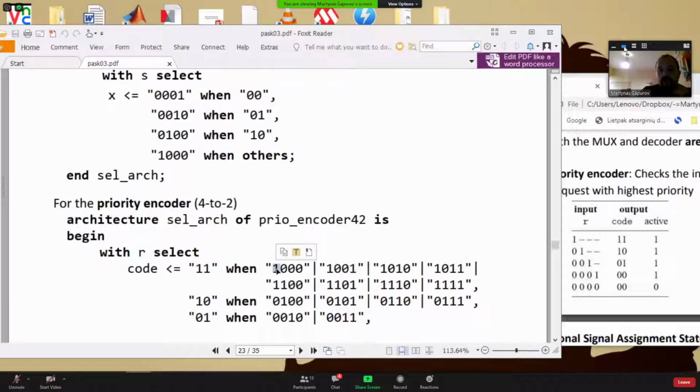for this bit, you can see that it could be obtained with a lot of different combinations of our control signal. So if we check only for one bit, it will not be mutually exclusive, and if we do not enumerate all of them, it will not be all inclusive. In this case, this stroke means logical or among all these conditions. So if any of these Boolean conditions is true, then we have our code equal to 0, 1.